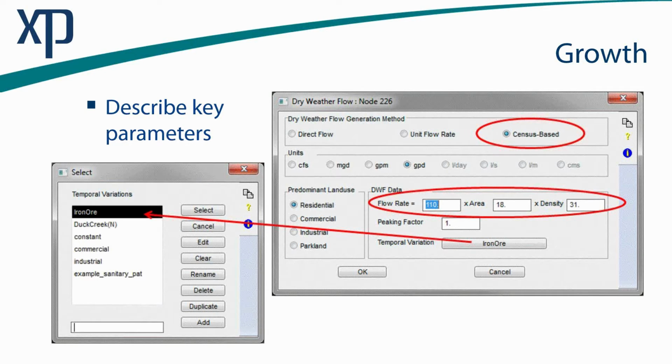We can look at how flows are derived from any given location. If I have a development area, do I have direct flows that I can measure? Do I have just simple unit flow rates, which is a very common simple tool? We go back to first year university, sewer engineer. Unit flows are very common in textbooks, or the really common one, which is census-based or population-based.